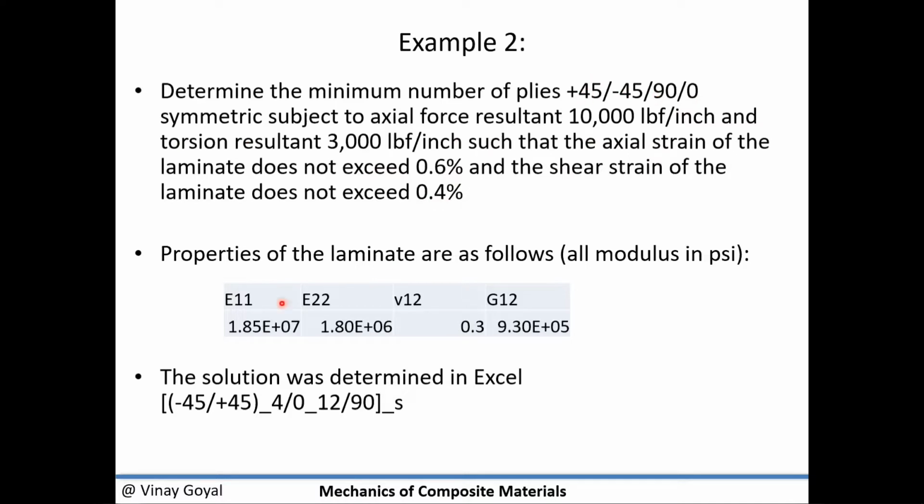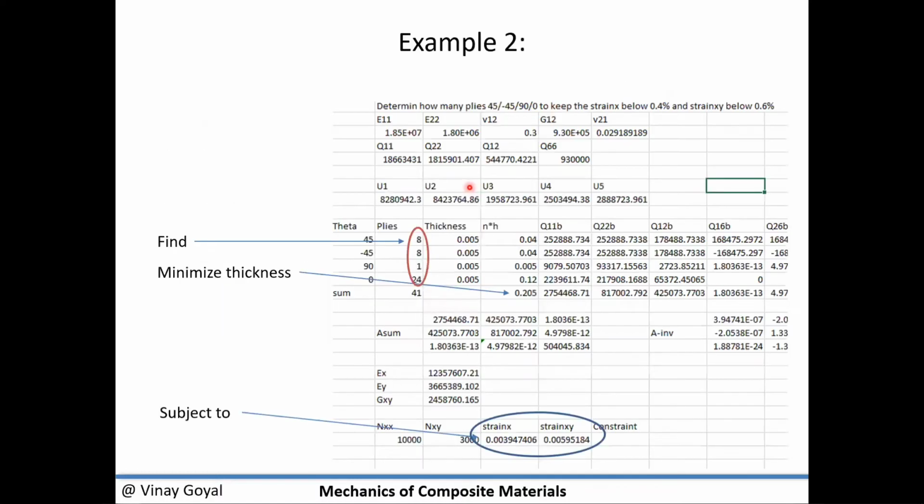And the properties of the laminates were given to you. Again, you can characterize its properties using the approaches that we've discussed, and that includes finding out the ply angles in the stacking sequence. And we'll talk about what approaches we have that will be great for using a good stacking sequence. But the first step is to figure out what ply angles I need. And notice there's no bending here in this example. Okay, so why don't we go to Excel and see how we went about that.